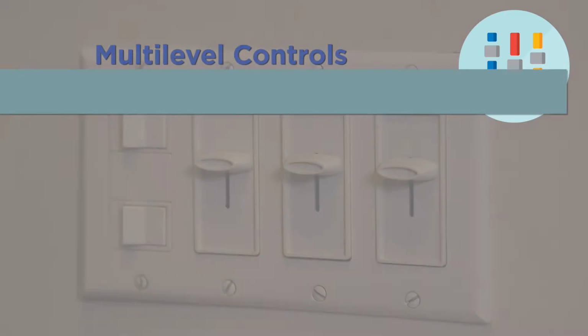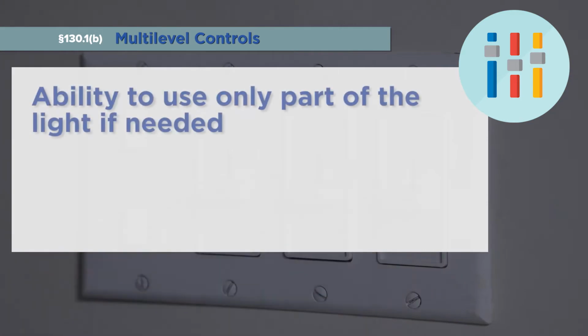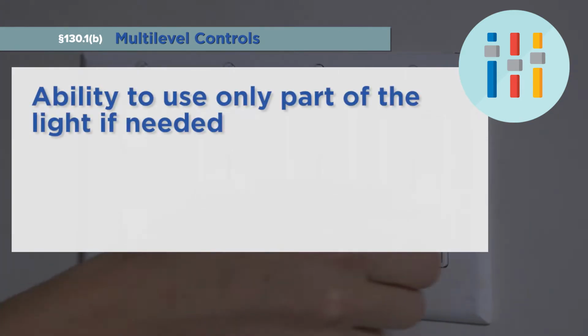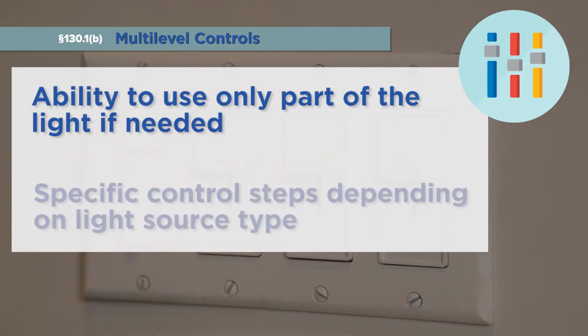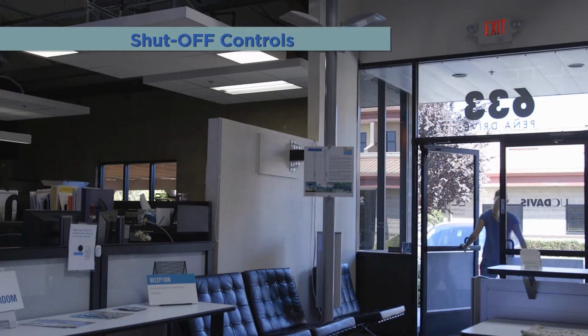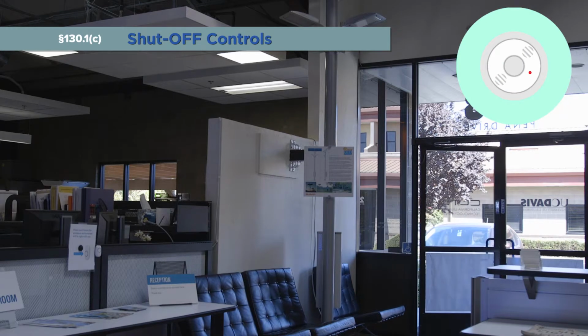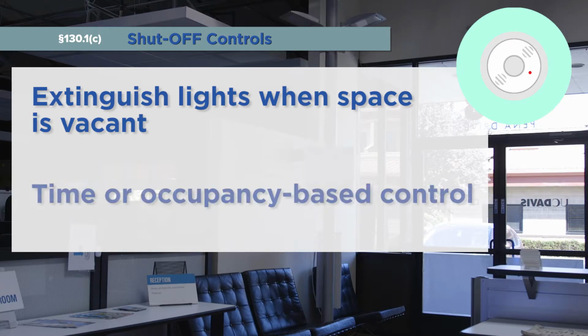The second control layer consists of multi-level lighting controls. These controls give occupants the ability to use all of the light, some of the light, or none of the light in an area. There are specific control steps depending on what type of light is installed. Shutoff controls automatically turn off or reduce light output when the space is normally vacant. They form the third layer of control required under the energy standards. Shutoff controls include time-based control devices as well as occupancy controls.